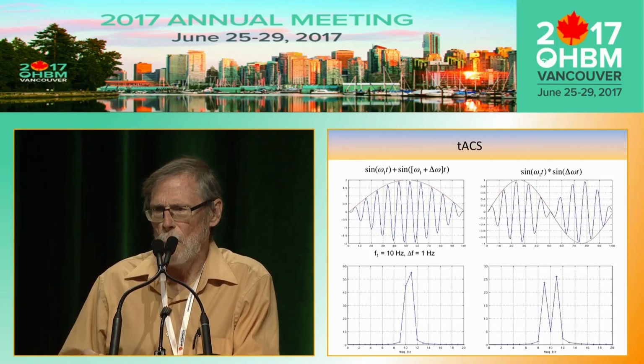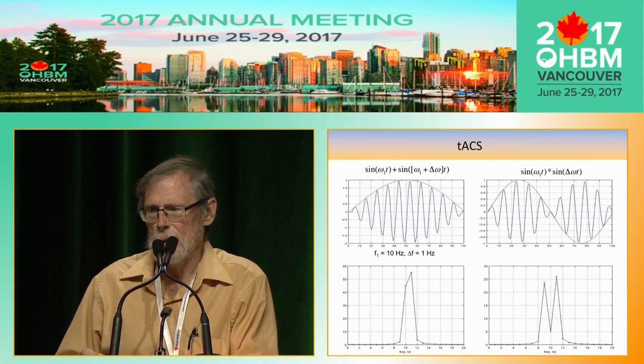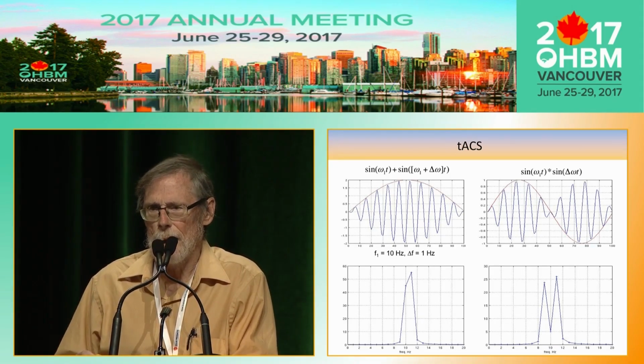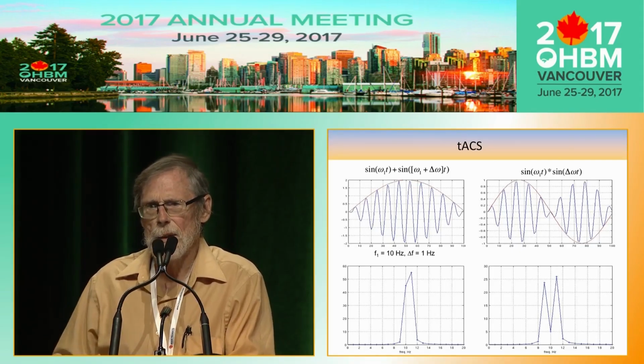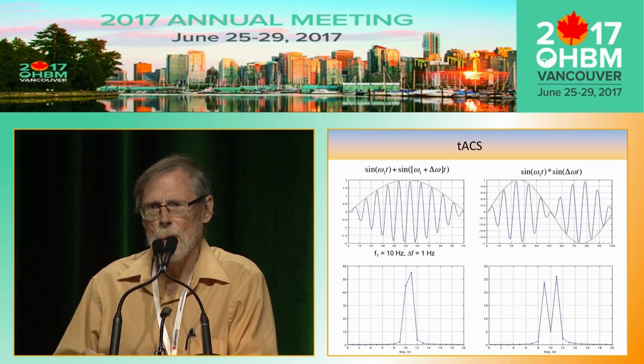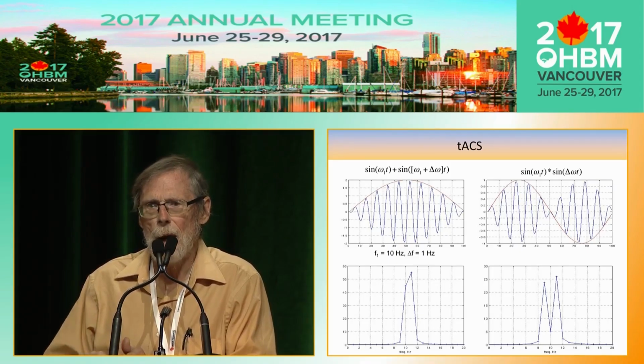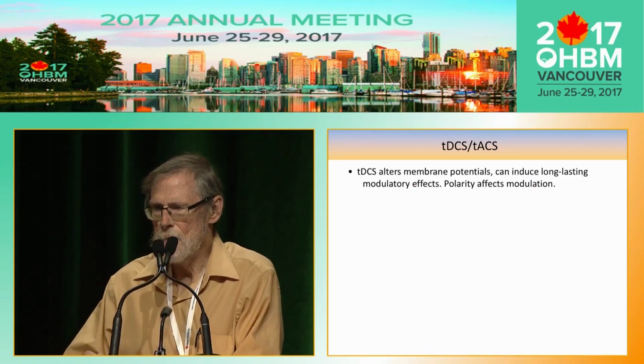The other example was using an amplitude modulated 10 hertz in this case. You see the 10 hertz carrier that is amplitude modulated at 1 hertz in this case. And again, the spectrum doesn't include any 1 hertz. It includes 9 hertz, the difference, and the sum frequencies. So it includes 9 hertz and 11 hertz. So it's interesting that the brain thinks there's a frequency present when it's not really present, and it required that low frequency modulation, even though it's not part of the signal itself.